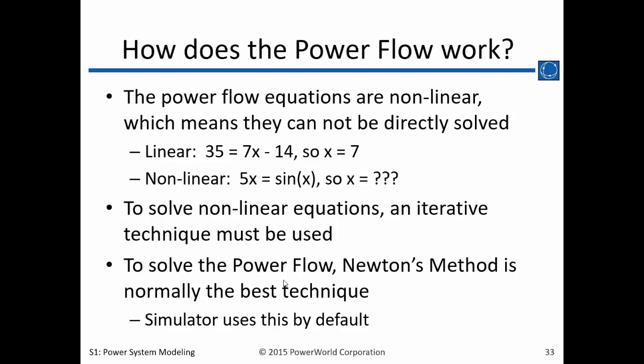Okay, so now let's talk about how a power flow works. The power flow equations are nonlinear, which means we can't directly solve them. Therefore, to solve the nonlinear equations, we have to use an iterative technique. To solve a power flow, Newton's method is normally the best technique, and we use this method by default.